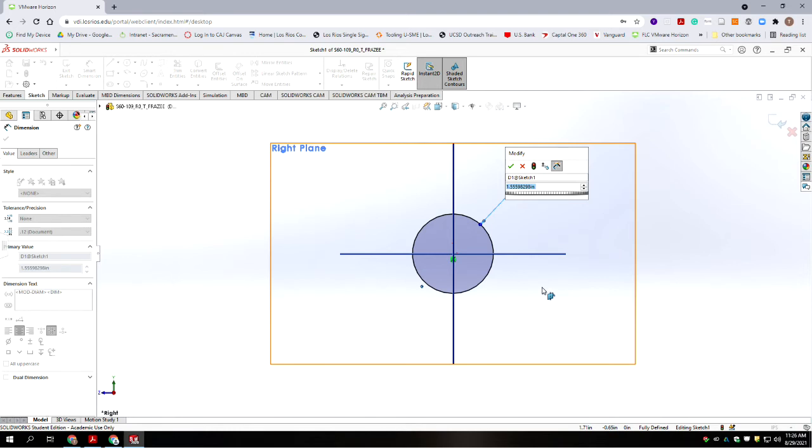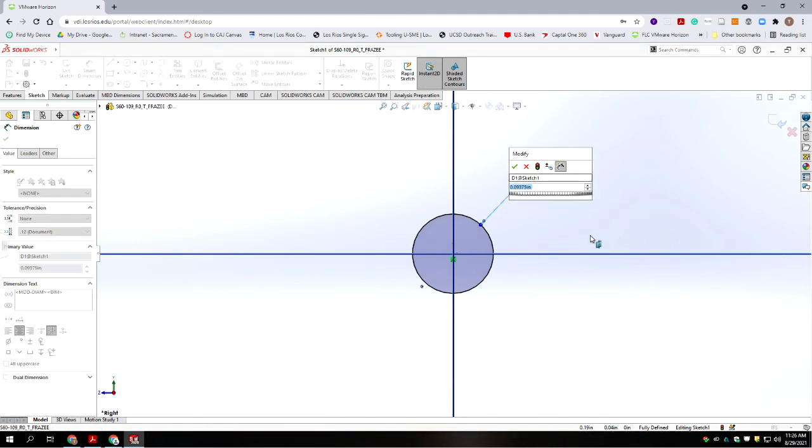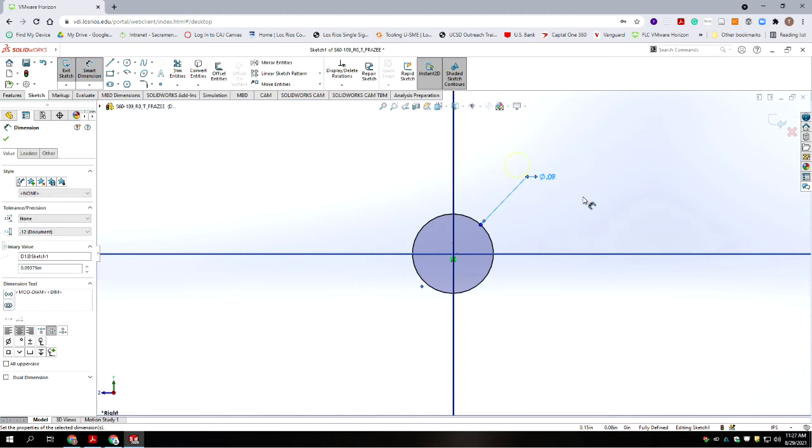The default size I happened to draw was 1.5 inches, and that's way bigger than what we're making. So again, that's 3/32, and you can actually put the math right in SolidWorks. So I'm going to put 3, division symbol, 32, and press enter, and it calculates it out. If I double click on this, you can see it calculates out to 5 decimal points. Now the display is rounding because it's only showing 2.